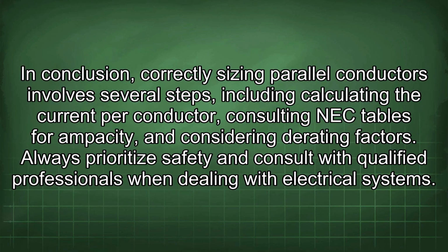In conclusion, correctly sizing parallel conductors involves several steps, including calculating the current per conductor, consulting NEC tables for ampacity, and considering derating factors. Always prioritize safety and consult with qualified professionals when dealing with electrical systems.